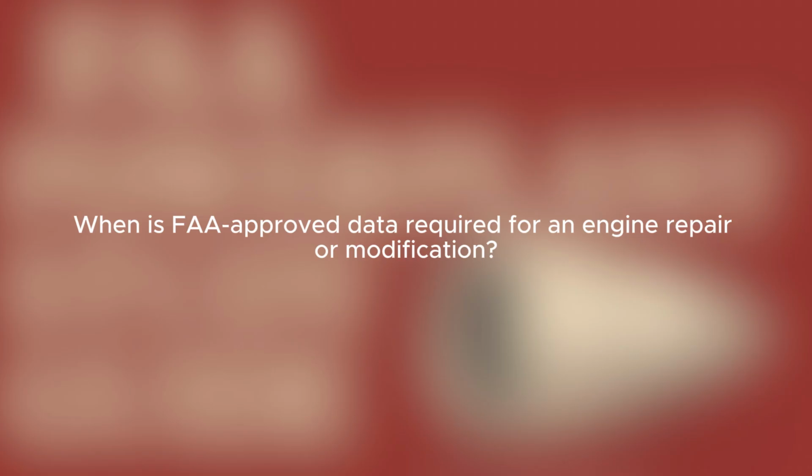When is FAA approved data required for an engine repair or modification? You must use FAA approved data anytime you perform a major repair or modification to an engine.